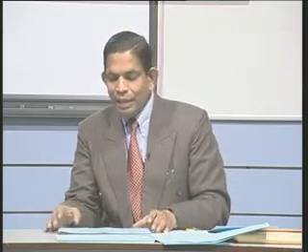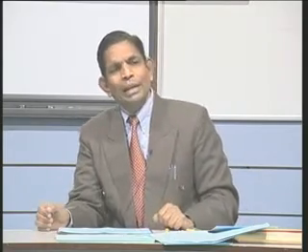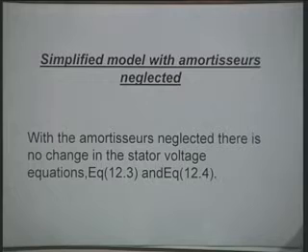Here I would like to caution you that many times people have considered the amortisseurs in the mathematical model, but we can make some simplification here by neglecting them. Now, the justification for neglecting amortisseurs is like this. One is that the synchronous machine parameters related to amortisseurs are generally not easily available.